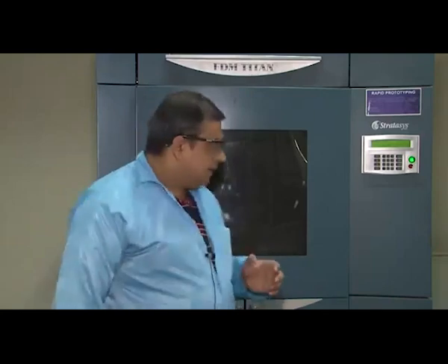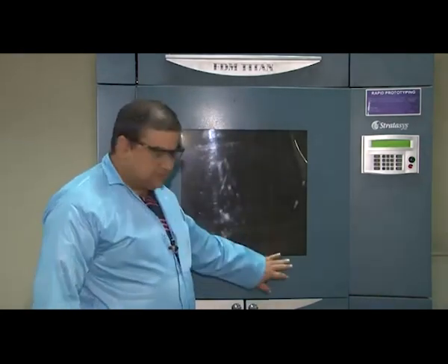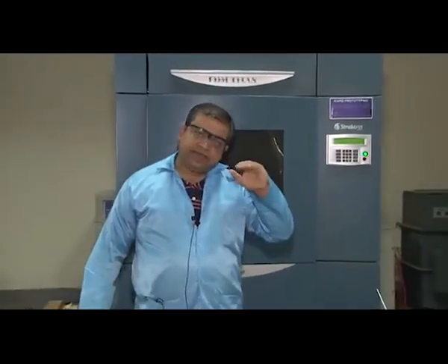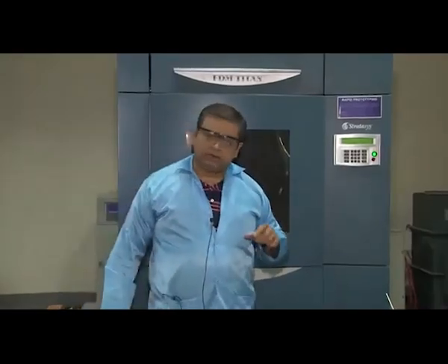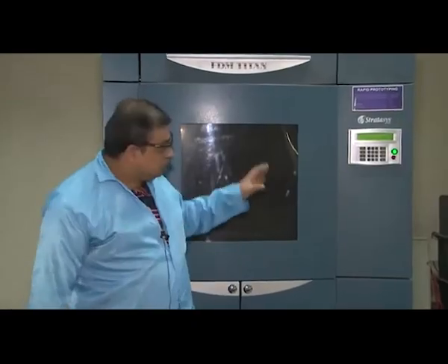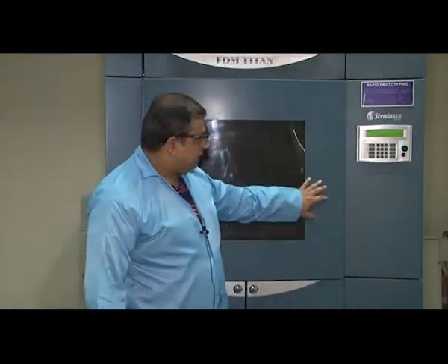So having said that, the question comes how this layered deposition model works. As I told you, the first step is about making a CAD file and sectioning the CAD file into slices or pieces. These slices could be close to whatever the resolution of the equipment gives. In this particular case, this machine handles two different materials, ABS as well as PC. For the ABS plastics, the minimum size of a slice which is available here is 125 micron, so 0.005 of an inch.